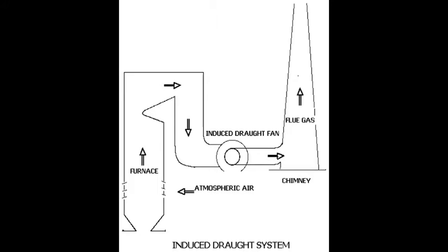In larger capacity boilers, where the flue gas passage is long enough and there are a number of passes, naturally system resistances are more, and we need to incorporate some evacuating device so that there is smooth flow of product of combustion across the furnace and after the furnace in the heat trapping zones, and we can evacuate the flue gas smoothly from the system through the chimney.